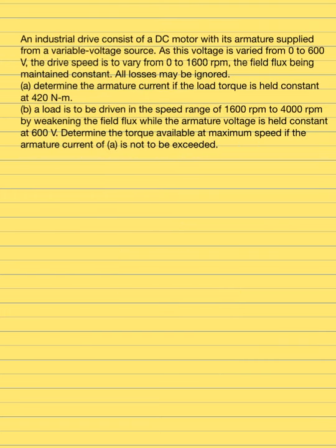Okay, this is again a question for a DC motor. And in this case it is not permanent magnet type, so you have the field side and you have the armature side. In order to draw the circuit diagram, this is where your armature is, and it is a motor. So these are the armature terminals, armature terminal voltage VA, and that's the current drawn from the terminals into the machine, and this is RA and this is E.